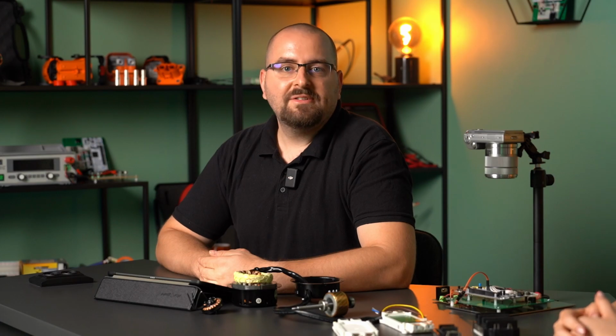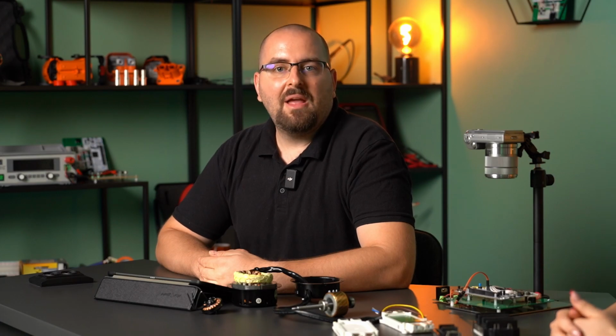Suppose you're given a motor with a datasheet that says the number of pole pairs is 2, and you want to run it from a 50 Hz mains supply. The synchronous speed is, therefore, 25 revolutions per second, or 1500 revolutions per minute. This means that the motor will spin a little slower than 1500 RPM at idle, due to the minimal losses in the bearings and air resistance, which we need to overcome with a bit of torque.